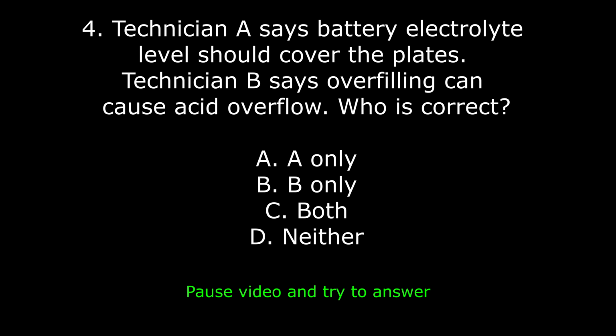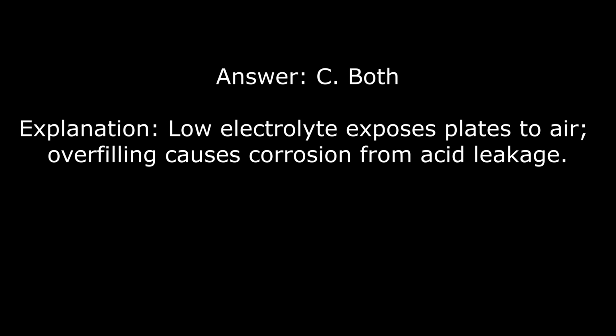4. Technician A says battery electrolyte level should cover the plates. Technician B says overfilling can cause acid overflow. Who is correct? A. A only. B. B only. C. Both. D. Neither. Answer: C. Both. Explanation: low electrolyte exposes plates to air. Overfilling causes corrosion from acid leakage.